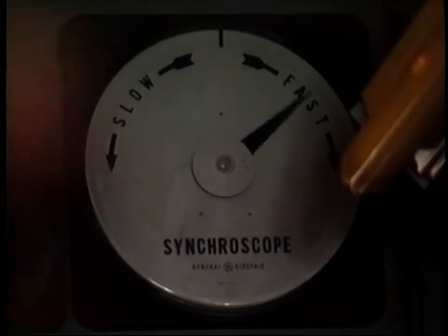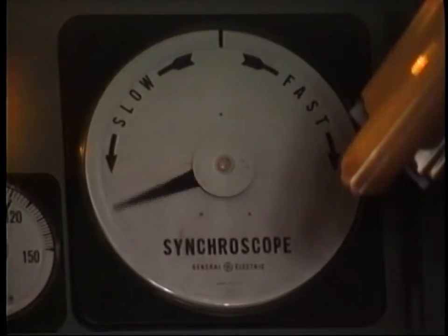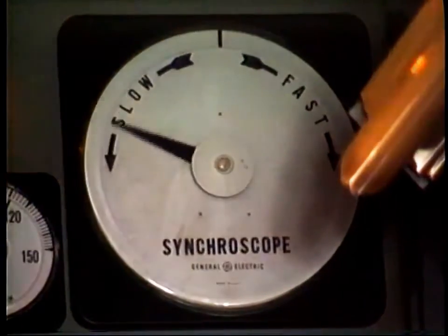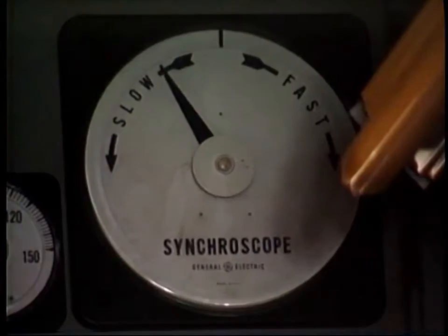Similar distortion of the windings may occur if the generator is incorrectly synchronized, that is, connected to the system when it is out of phase with the system. One problem that can occur on generators is the loosening of the windings with resultant vibration and increased temperature rise and perhaps damage to insulation. Checking the conductor wedges for tightness is an important maintenance item during overhauls.